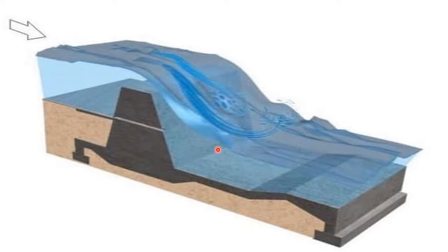Here there will be a water cushion, same as in the case of a trapezoidal notch fall that we have studied earlier. So, this is a water cushion. As we can see, the floor is depressed here, and this is a downstream canal bed. So, water will be simply flowing over the crest wall and falling downwards to the downstream side.